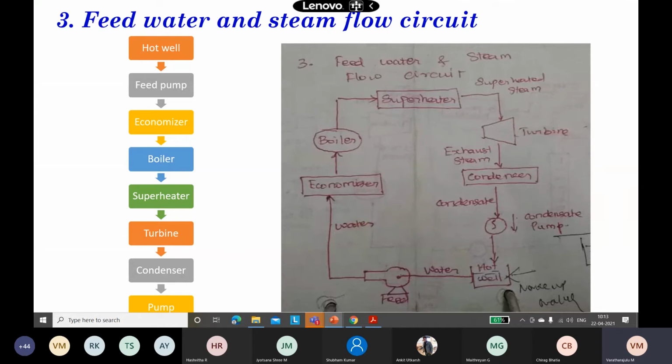And we have the electric generator. The electrical generator is directly coupled to the turbine, and it converts the mechanical energy of the turbine shaft into electrical energy, and it consists of electrical windings. One is mounted on the turbine shaft, rotating within, called the rotor. The other is fixed to the floor and is called the stator. We have rotor and we have stator. The relative motion of rotor and stator generates electricity of 11,000 volts.